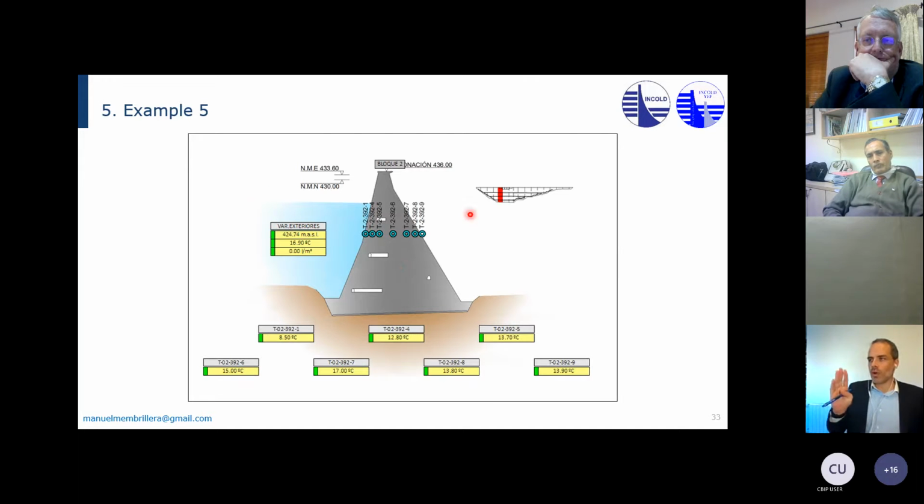Longitudinal joint. So apart from the block joints, these vertical joints along the dam, from one abutment to the other, they were concerned about a crack being created here because the dam is massive. There's a lot of surface in contact with the foundation.